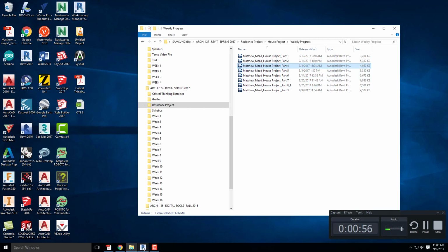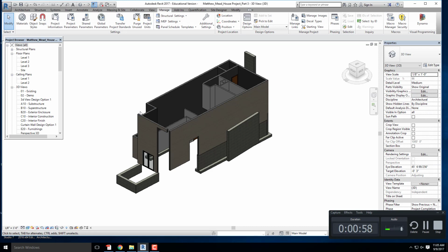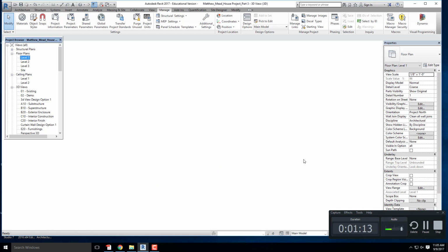Let's see, I may not have used this term in the past, but witness lines are the little blue dimension lines that you see when you're editing your walls and your windows. Those are the dimensions that you can click on and that will ultimately affect what you're working on.